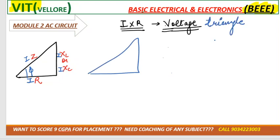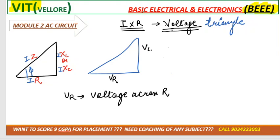In the voltage triangle, on the base we can take VR, right? VR is the voltage across the resistor, right? And on the perpendicular we can take VL or VC. VL is the voltage across L, VC is the voltage across C, right?